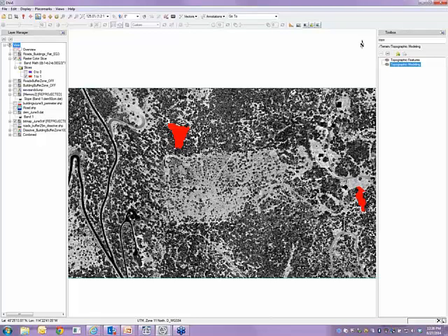The thing you want to make sure you're doing is getting the bare earth surface and not the surface features. So LiDAR is actually a really good source of information to create those types of drainage plans, and then those become really good midstream input for something like, I think that customer was using an ArcHydro tool or some other hydro tool, to see where the water would actually flow, the local sinks, and all that kind of stuff. So it's a really good way to get a good input layer for some of those modeling projects downstream.